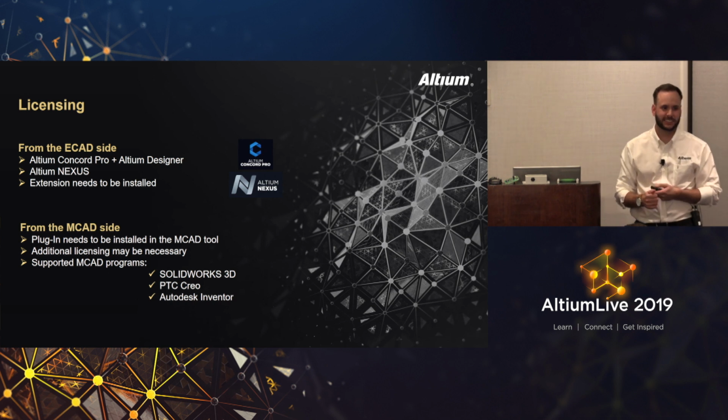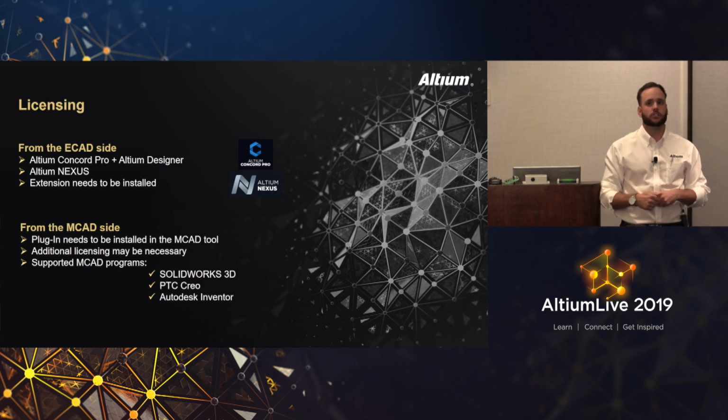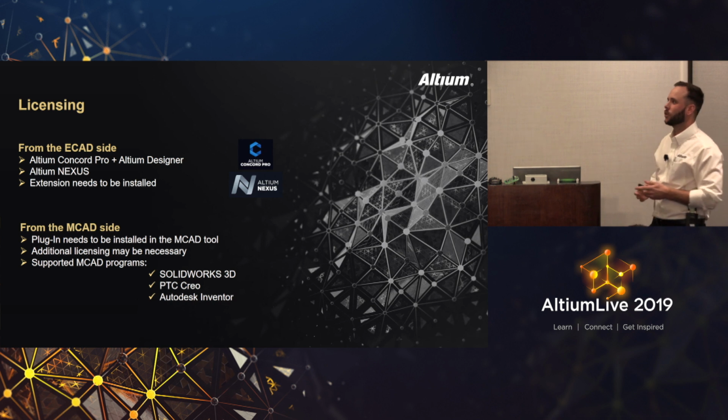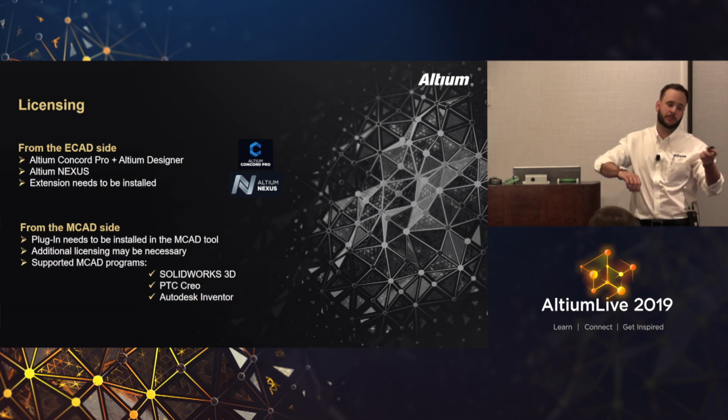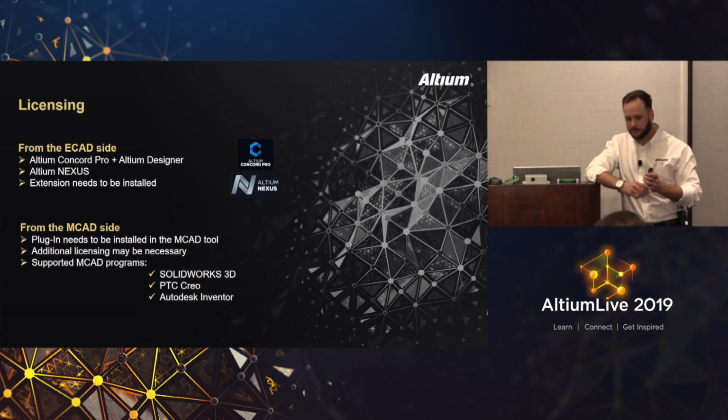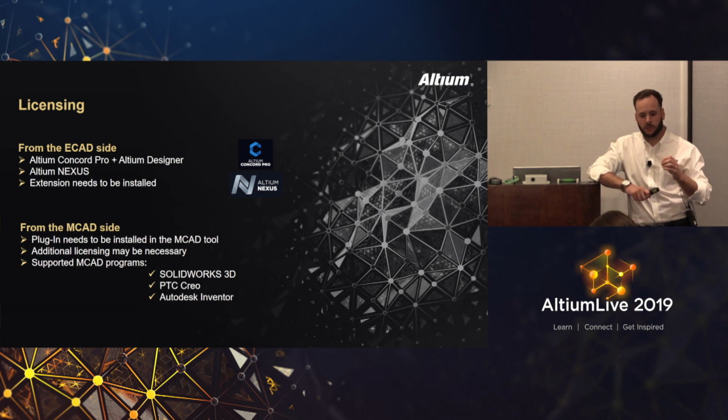Where are you storing the files on the MCAD side? So that is, and this is always the gray area, and I'm happy you brought it up because we were going to talk about it anyways. Right now, the MCAD CoDesigner's main purpose is collaboration and communication. It doesn't have a dedicated storage method right now for the SolidWorks files. What happens right now is that all of these solid parts that came from the 3D models from Altium went into SolidWorks and created a solid part.